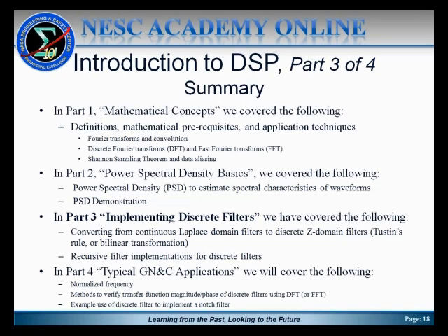And we concluded that part 2 presentation with a demonstration of a particular waveform where we built a time series waveform consisting of a number of sinusoids, a bias, and a random component, and showed how the PSD capability can be used to identify the signal characteristics of that aggregate time series.